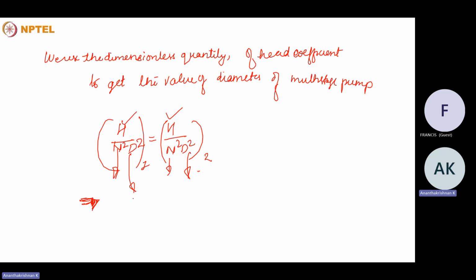Dimensional geometry, kinematic, as well as dynamic similarity. So from this one, we can calculate the diameter D as the H value. At RPM 2000, this diameter is 0.3, H here is 28.71. From the specific speed analysis, we have calculated the H value per stage, and then the RPM in this case is 1500, and we calculate the D2.